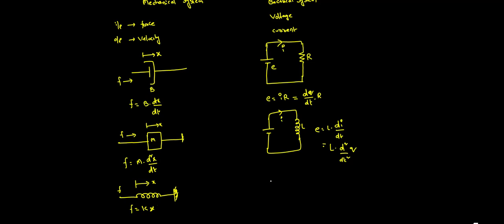So what is the thing here? It is equivalent to the capacitor. How is it a capacitor? It is very simple. Here we have I, and this is E. So E is equal to 1 by C integral I dt, where I is equal to dq by dt. So the integration cancels, and you get q by C only. If you write in terms of q, integral of dq by dt into dt, integration and differentiation cancel. Finally, you get only q by C. That is how you can write the equations in this analogy form.